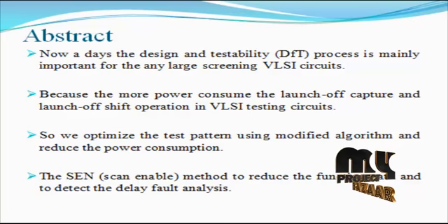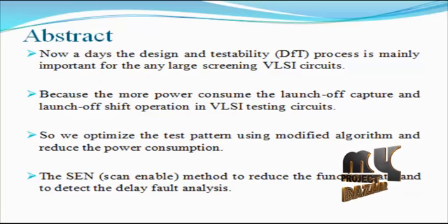We developed the cost and quality patterns in a power unaware manner. One is launch off shift, one is launch off capture, and another is mixed testing to be followed. The proposed DFT support enables a partition approach where any set of patterns generated in a power unaware manner can be applied to the design one region at a time, reducing both the launch and capture power in a design flow compatible manner. This way the test pattern count and the quality of the optimized patterns are preserved while lowering the launch and capture power.